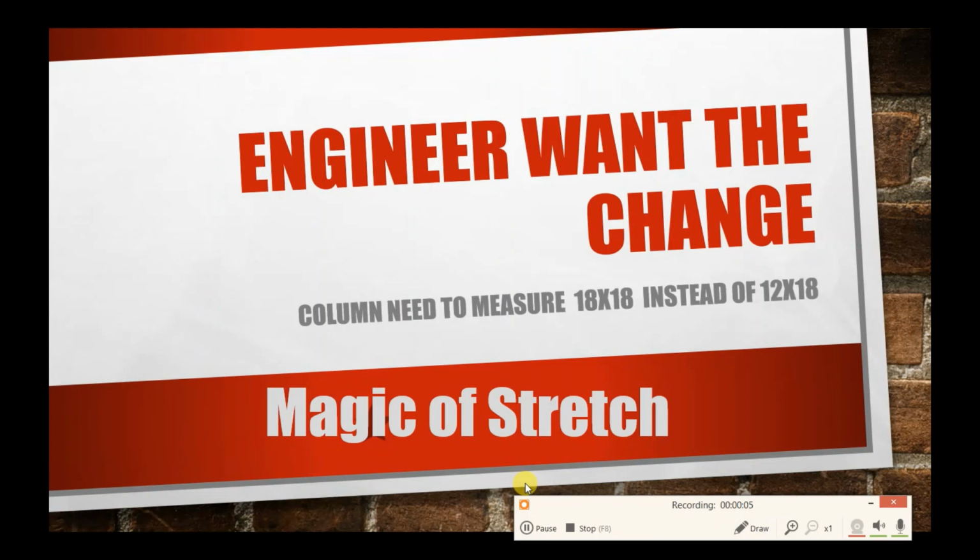So now the engineer wants a change. What has happened is the engineer came and said to us that the column needs to measure 18 by 18 instead of 12 by 18. Which means the base plate is so small and the anchor bolts are the wrong plates. So now what is needed is that we need to change our column from 12 by 18 to 18 by 18, which means we have to move 6 inches.